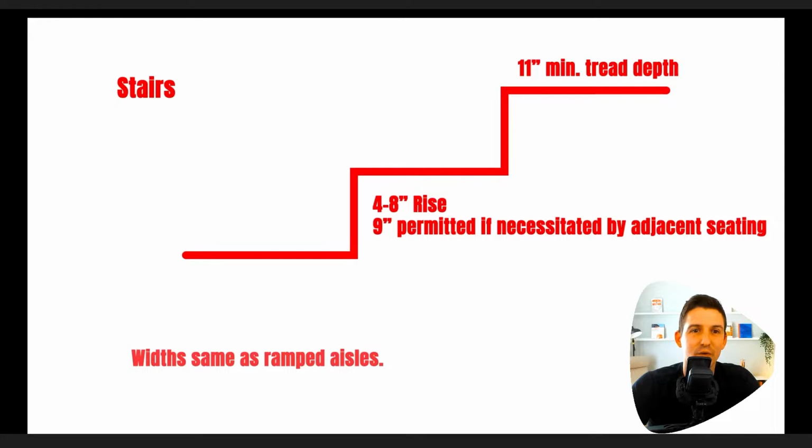That's egress for assembly seating, and it's not so bad if you digest it in chunks. I would just think about the thresholds throughout this. You can go on the very conservative side, or if you need to fit a lot in a tight space, take into consideration what your options are. All right, we're moving on.